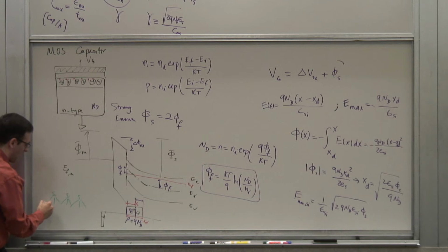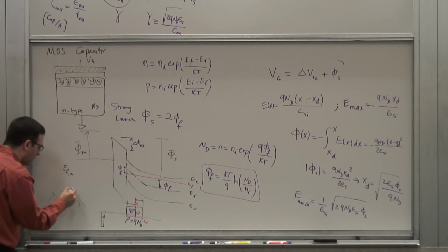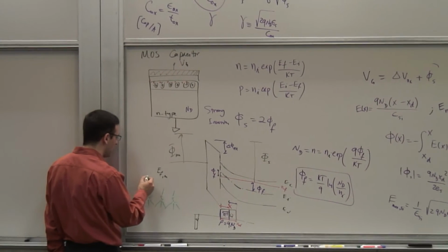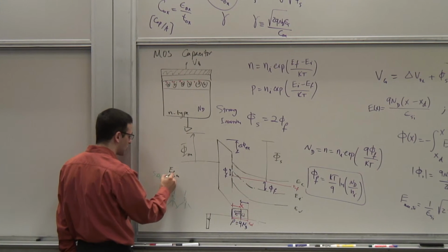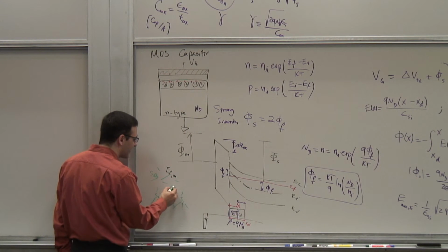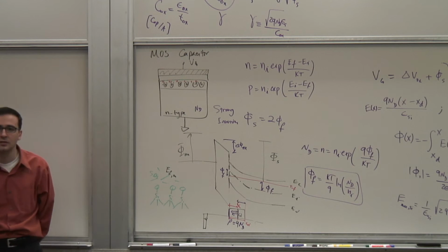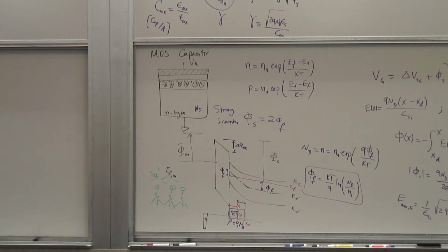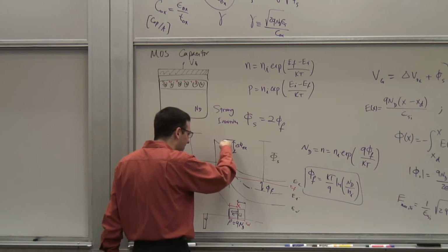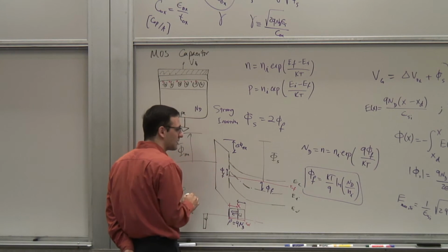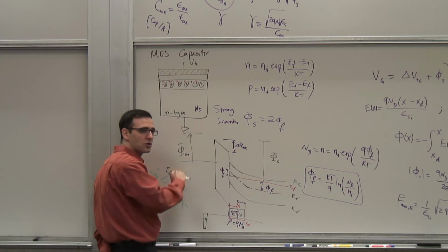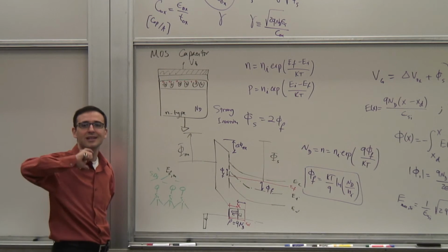Each one of them, 3 of them are happily bonded to other silicon atoms on the bottom side and the side, right? But the 4th ones are going into something which is different, which is the silicon dioxide that has a different structure and all those things. So there are these dangling bonds here, which can actually attract and trap a second electron, and form a charge center at the surface. So you have this layer of constant electric charge which is not mobile at the surface. And that creates an additional voltage drop. You need to have an additional voltage.